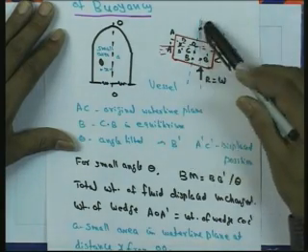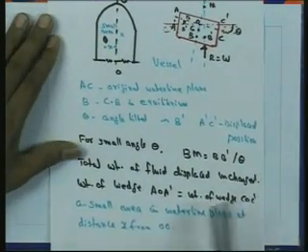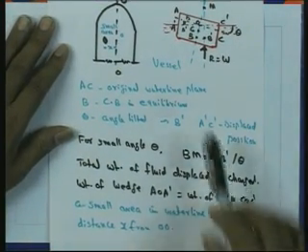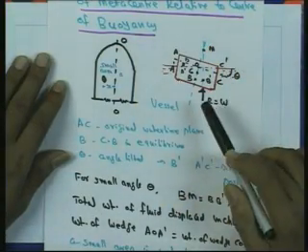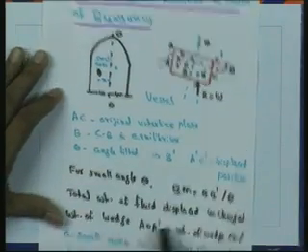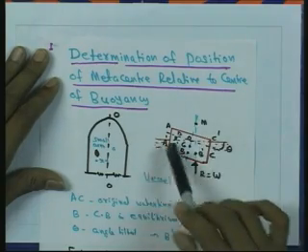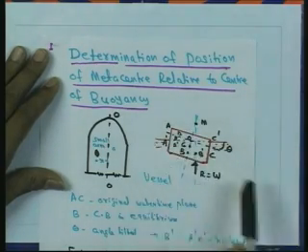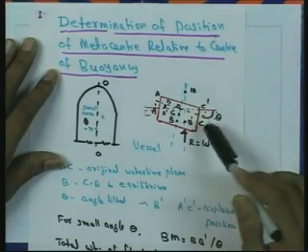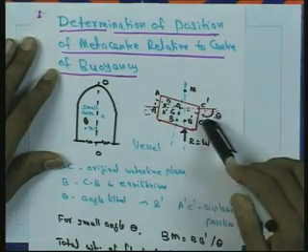The total weight of the fluid displaced is unchanged, since we are giving only a small tilt to the vessel. The weight of the wedge, with respect to the fluid displaced, is equal to the weight of the wedge C dash O C, that is, C O C dash.